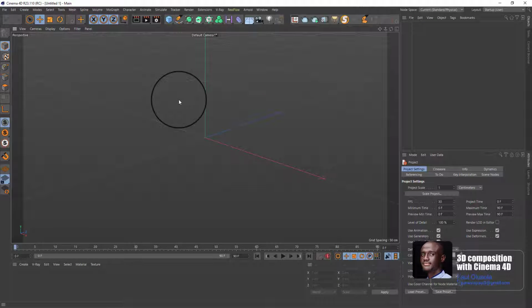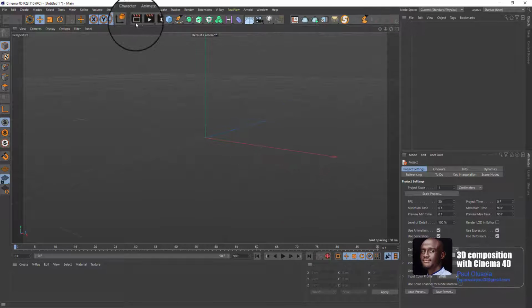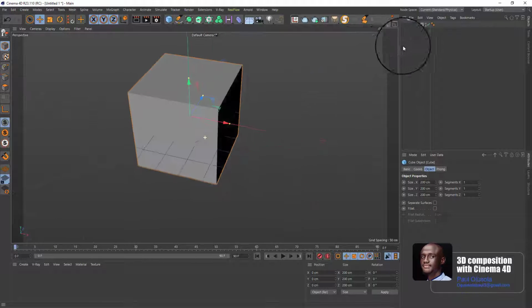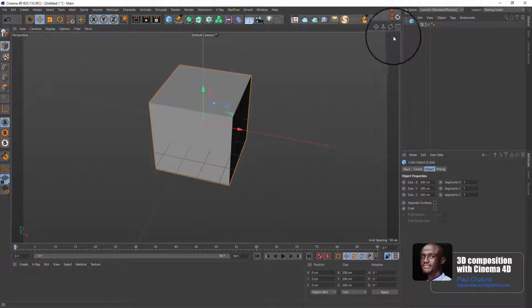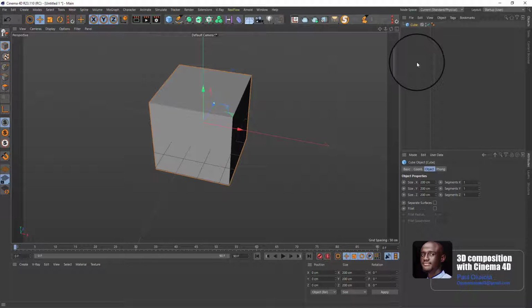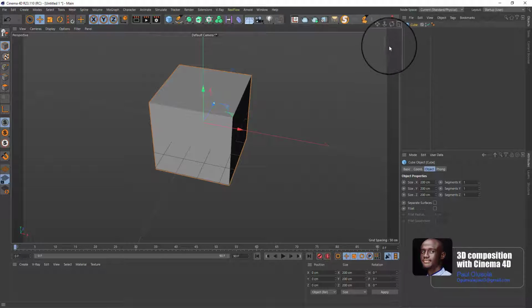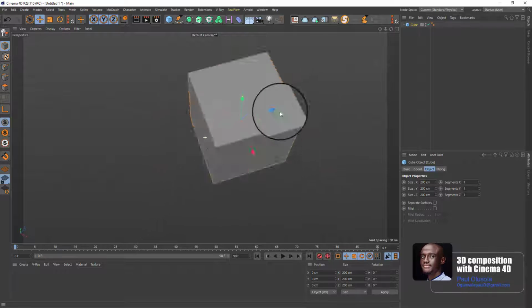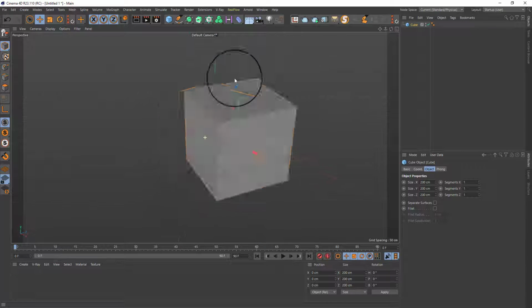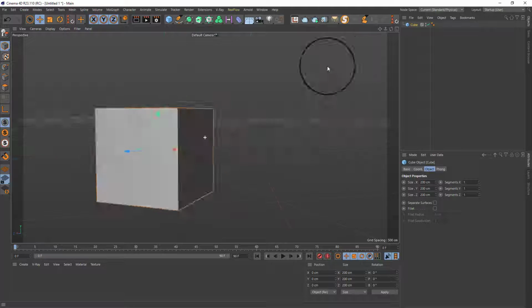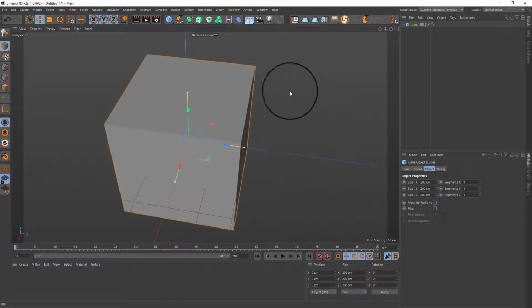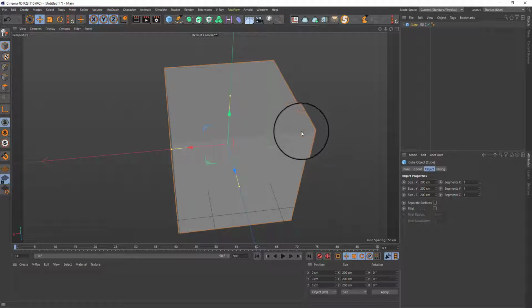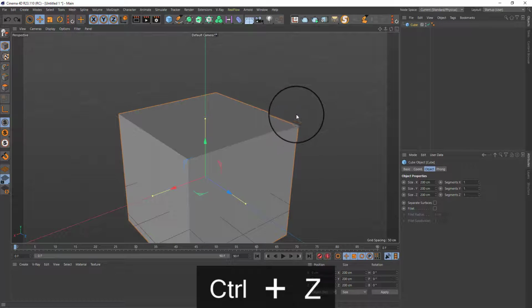So yeah, this is the Cinema 4D interface. To navigate, this is rotation. You can just drop a cube. This is rotation here, zooming in and out, move. I'm using a graphics tablet. That's why I don't want to generalize the way I often navigate. So you also can use a mouse. Holding Alt and your left mouse button, I believe you can rotate. Then two is zoom, one is pan, three is rotate. So it is relatively easy.